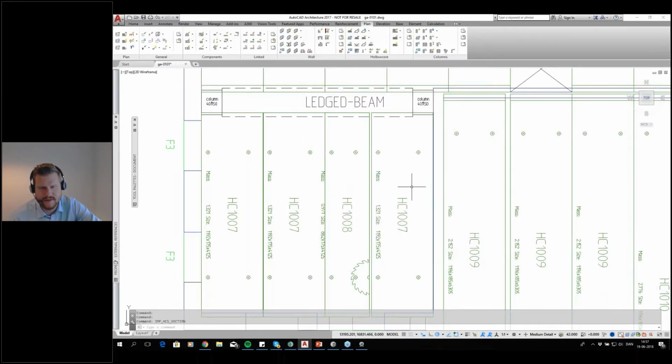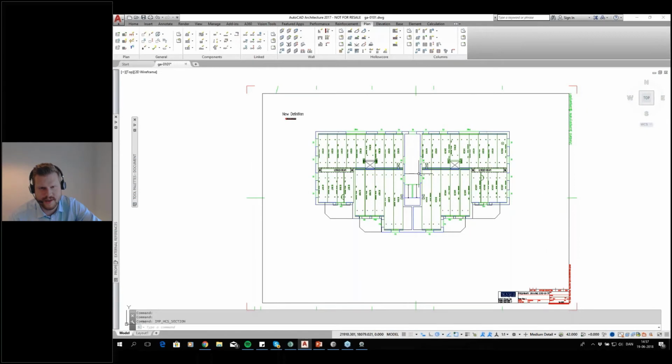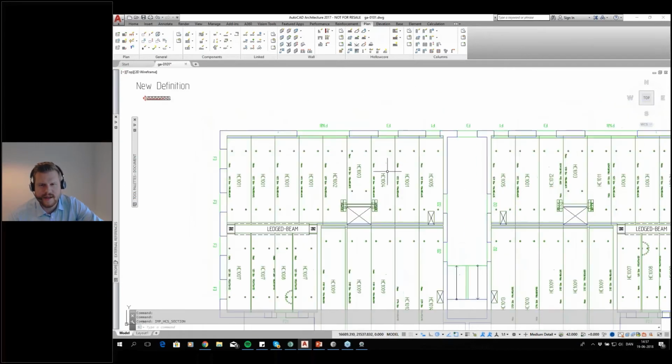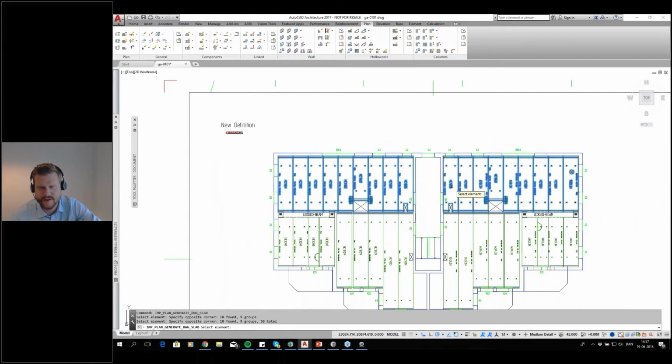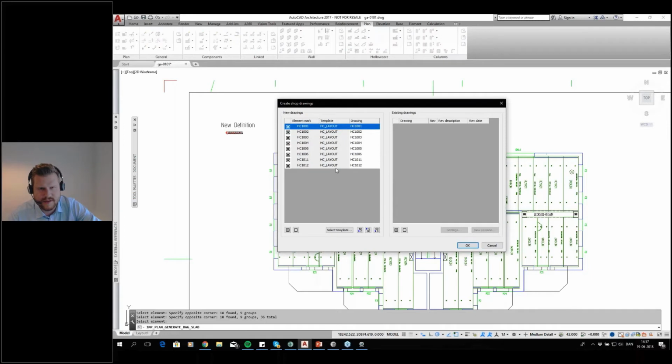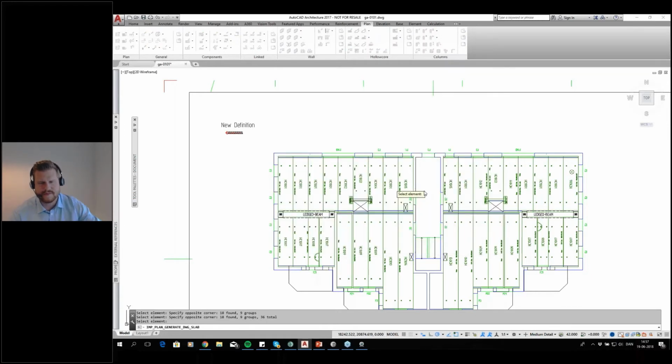There we go. We don't want to spend too much time on this, but that means that we actually have the whole thing now. Let's say that this floor is actually finished now. Some of you may not use drawings, a lot of you do. Let's just create drawings for these ones at the top. So now we'll say use the template drawing, this is fine. And it will create drawings for all of these Hollowcore. These drawings, of course, we can use later when doing planning and everything.